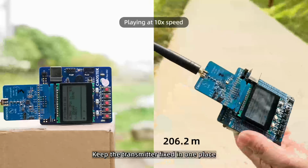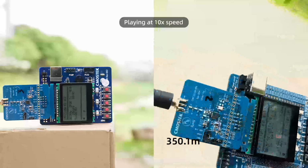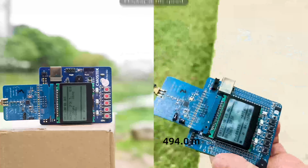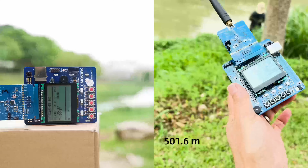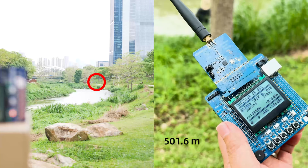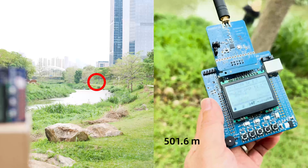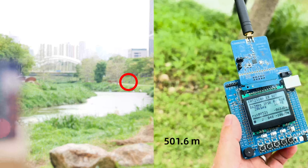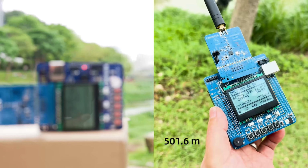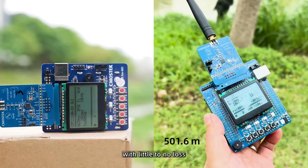Keep the transmitter fixed in one place. Turn on the receiver first, then turn on the transmitter. Move the receiver to a certain distance away. The packets received should match the packets transmitted with little to no loss.